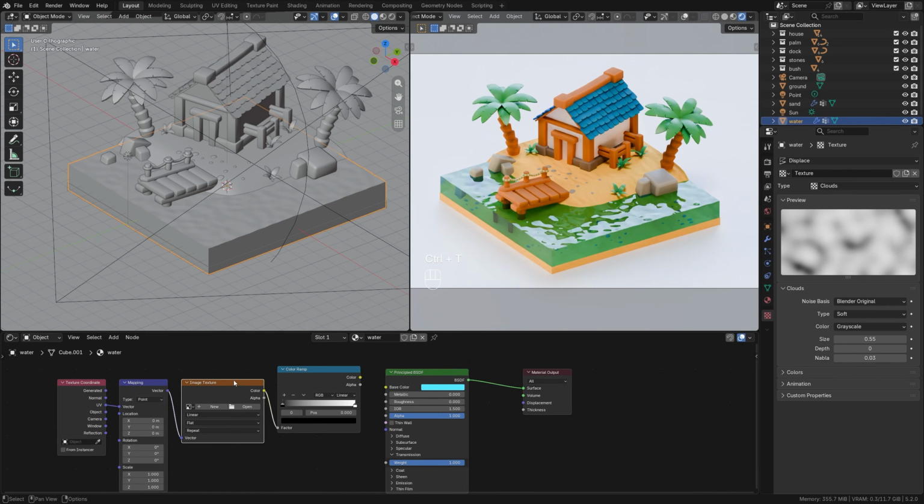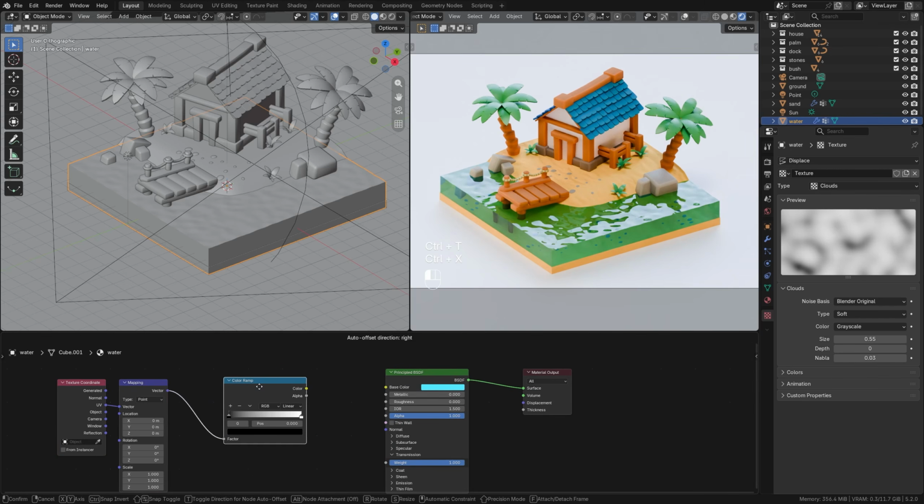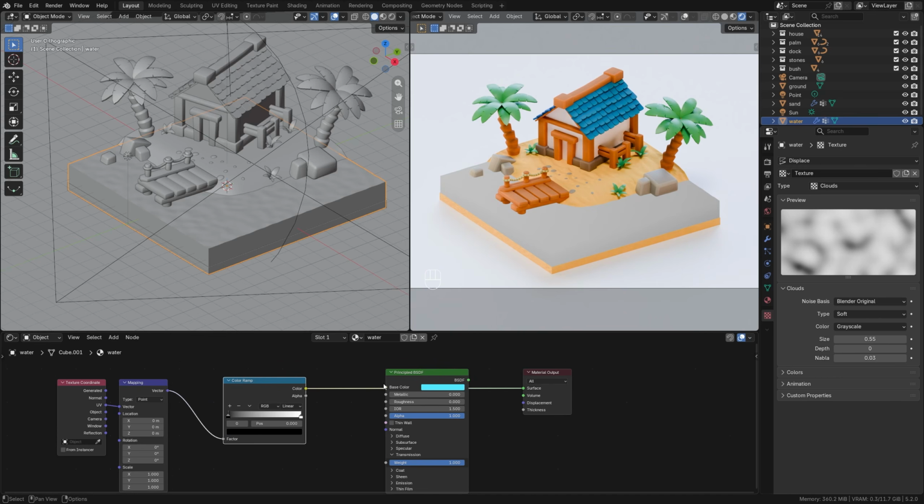With Ctrl+T, we add coordinates to it. And if we, with Ctrl, Shift, and left mouse button click on Preview, we see what gradient turns out for us. We turn on here Generated Texture and can adjust colors. Let's slide the white slider here and possibly rotate. As the first color, we take our already set up one. Let's move it here. And the second one can be made a little darker.